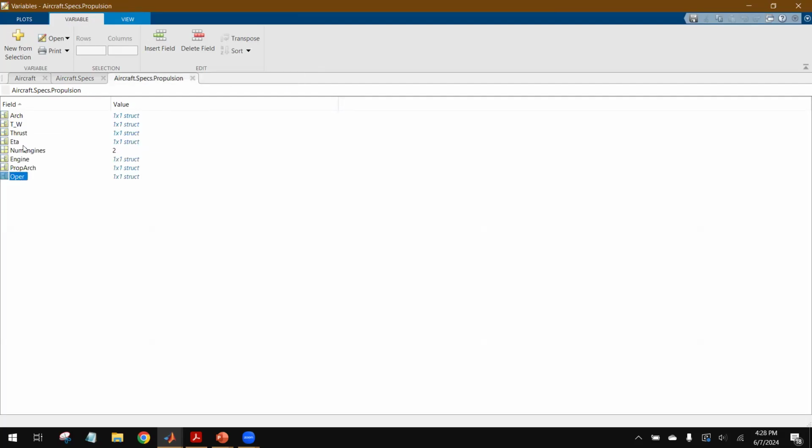And then, if we look at ADA for the efficiencies, we have the propeller efficiency, and then we also have some of the component efficiencies multiplied out. So the 72% represents the gearbox and propeller efficiencies being multiplied, and the 0.912 represents the combined efficiencies of the power converter and the electric motor.